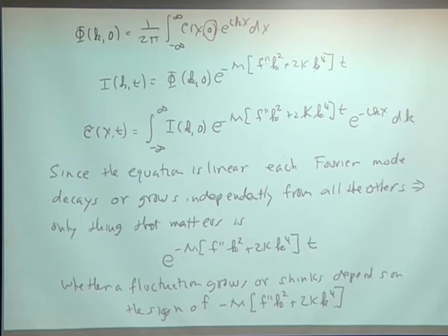Okay, so before I turn the page, I want to also point out something. If you go back and look at this equation here, you'll see that the linear theory says that the growth rate of a fluctuation will go exponentially in time, with an amplification rate given by this term here. But it's exponential. It's not a power law. It's exponential in time. And that's one of the predictions of the linear theory of spinodal decomposition, that you have this exponential growth in the fluctuation amplitude.